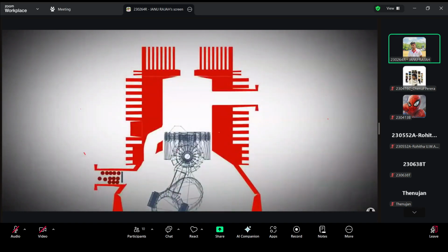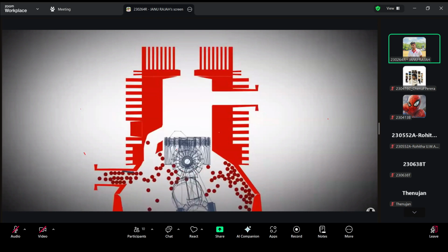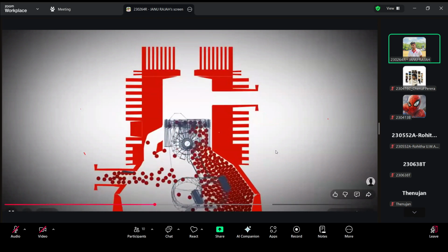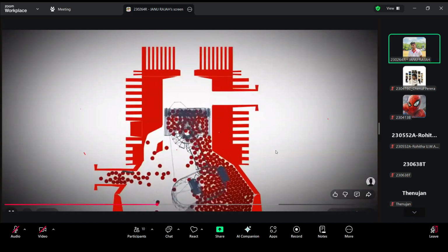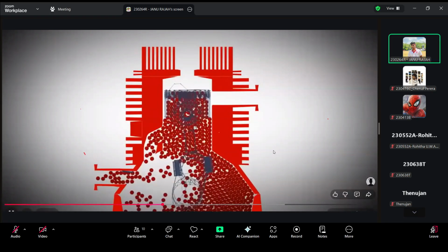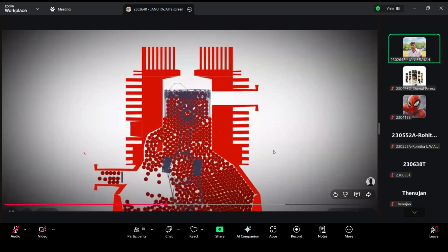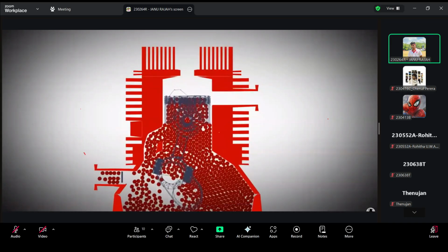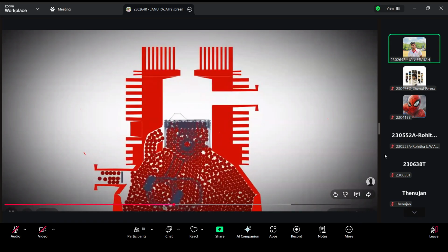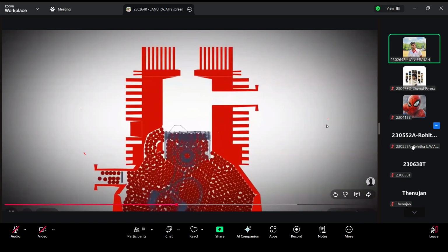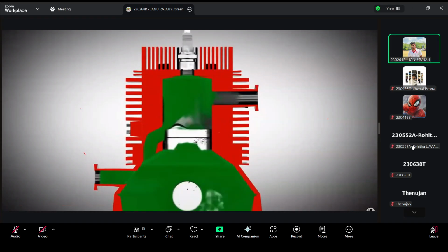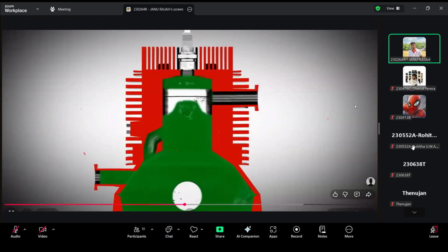The volume reduction in the crankcase can be very easily explained using small spheres. The spheres represent the fresh mixture. The mixture is sucked into the crankcase through the piston moving upwards. When the piston then moves downwards, no additional fresh mixture flows in and compression takes place because the volume of the crankcase is decreased. As a result, the fresh mixture makes its way into the combustion chamber via the transfer port. The engine shown here operates according to the principle of cross-flow scavenging.